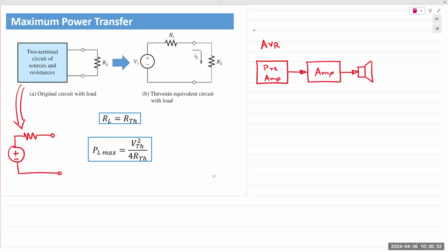So if you're self-installing a system, that is something that you need to keep a lookout for. If it's a pre-built home theater in a box, the speakers are already matched. Headphones need a lower volume, they need lower current so as to not load your mobile devices. So wired headphones have an impedance of about 32 ohms, at least if your phone has a headphone jack nowadays.